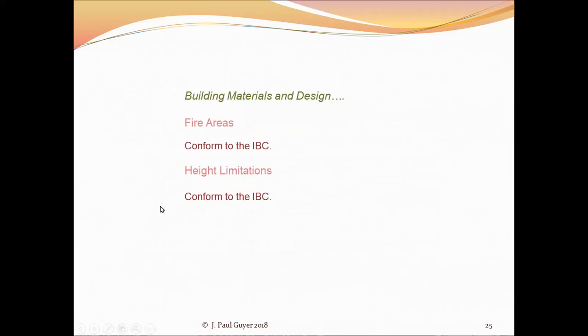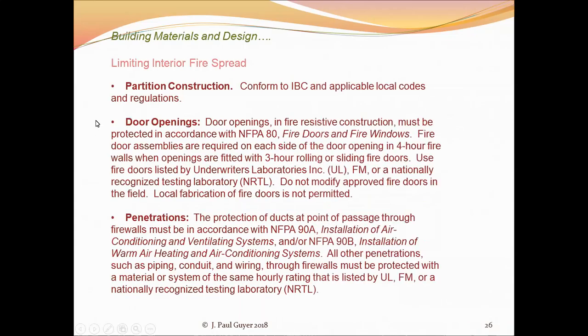The fire area, we'll come to that in a moment. A point to keep in mind as far as these partitions in your building are concerned, walls, ceilings, floors, is that if a partition between one area of occupancy and another area of occupancy is specified by code to be 1 hour fire resistive construction, 2 hour, 4 hour, whatever, that means everything in that wall needs to be of that fire resistive construction.